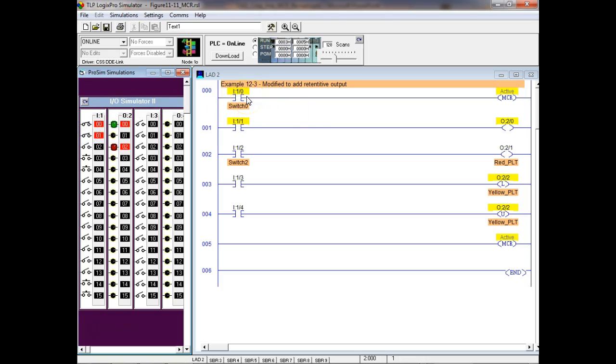And then when I hit that e-stop button, not only would it kill the power to my outputs, it would also kill the outputs themselves, right? You understand? Except for the retentive contacts. And that's the problem we have. So right now, this output right here would be turned on, and this output right here would be turned off, right? I mean, I'm sorry, it would stay where it's at.